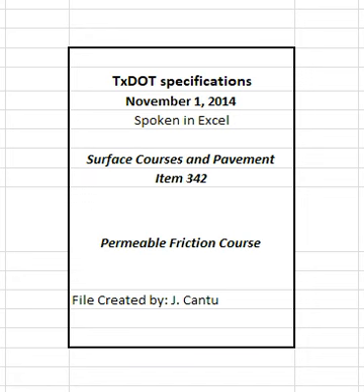4.7.3.1.1 Thermal segregation. 4.7.3.1.1.1 Moderate. Any areas that have a temperature differential greater than 25 degrees Fahrenheit, but not exceeding 50 degrees Fahrenheit, are deemed as having moderate thermal segregation. 4.7.3.1.1.2 Severe. Any areas that have a temperature differential greater than 50 degrees Fahrenheit are deemed as having severe thermal segregation.